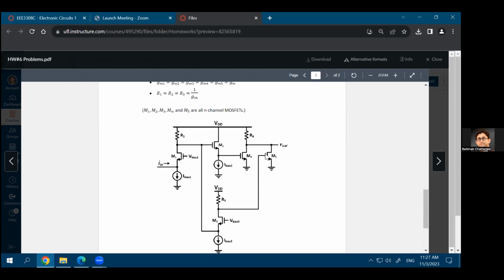So again, you can find out the gain of this stage and the voltage that is available at the gate of M5. Now M4 and M5 are both common source stages, right? Your source is grounded, input is applied at the gate, output is taken from the drain. They are both common source stages. Now for the common source stage, you know the voltage at the gate for both of them. You know the voltage at the source, so you know the VGS. And you also know the current that will be flowing at the drain terminal of these two. Because the drains are connected together, the currents will get added together. KCL. The currents will get added together, and then multiplying that current with the resistance connected at the drain, you'll get the final output voltage. Current multiplied with resistance gives you voltage.